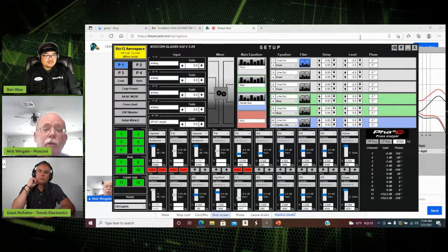It does work. It gets it really, really close. It doesn't mean that you're done, but it means you're close. Basically how it works is you set it up, you turn it on, and you click on the left tweeter. It'll send a test tone to the tweeter, and it measures it and sets the delay automatically. You measure every single solitary speaker in the car individually, and then you click send to DSP, and your time alignment is done. It takes literally 1 minute to do.